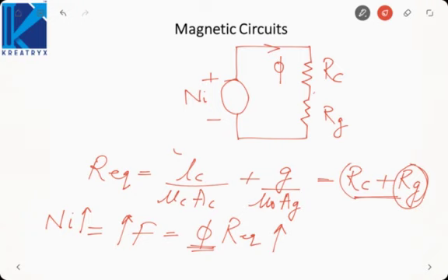This current is called the magnetizing current. Why magnetizing current? Because this current is responsible for magnetizing the core or making the core magnetic, that is developing a flux inside the core. Making it magnetic just means inducing a magnetic field inside the core. This current is responsible for such behavior, hence it is called magnetizing current. So remember, as air gap is increased in an electrical machine, magnetizing current increases for a constant flux.